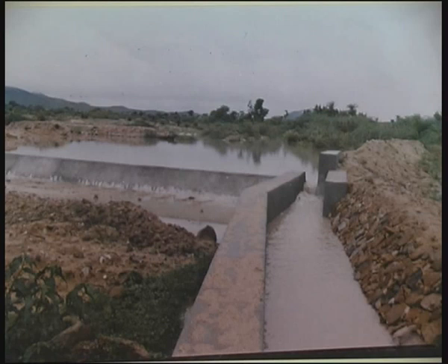The second reason is the cost of the structure is quite high, varying from 1 lakh to 3 lakhs rupees, and the corresponding increase in recharge through a water spread of about half a hectare to 1 hectare is not cost effective. So therefore, if it is intended to recharge significantly in a cost effective manner, we should not resort to a cement based check dam in the valleys where there is a good amount of groundwater already.